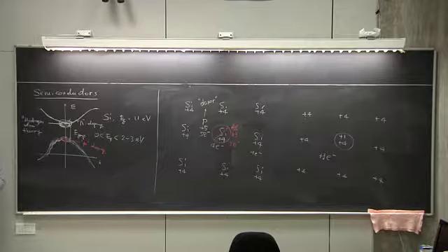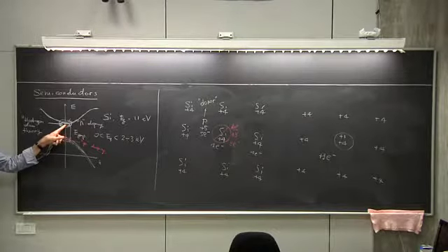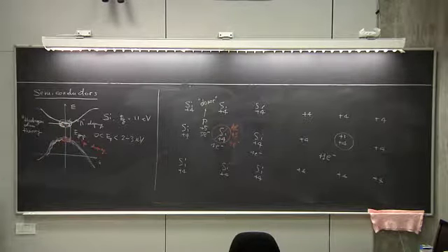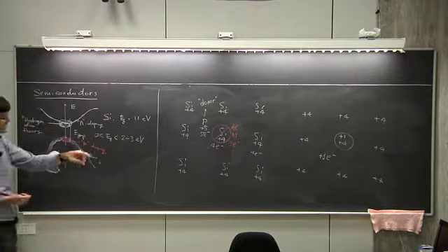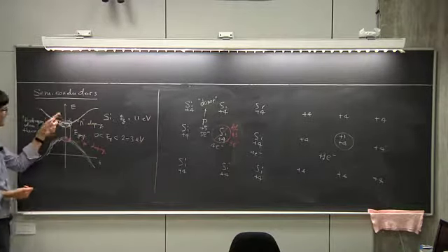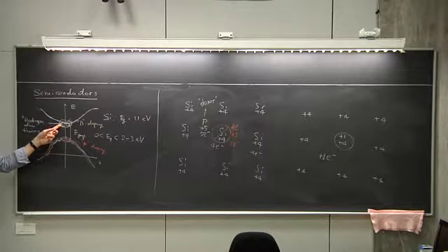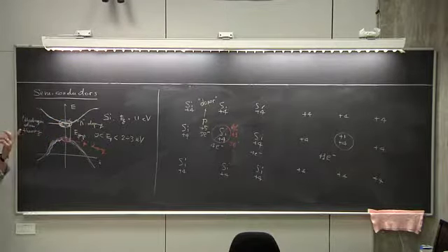Do we have a possibility of, when we dope silicon with aluminum, instead of having an electron in the higher state, to widen the energy and then to create another set of states so that the electron will stay there? Okay, so your question is whether this mechanism is only useful to add additional electrons, or whether it's also a mechanism to add additional states in the system.